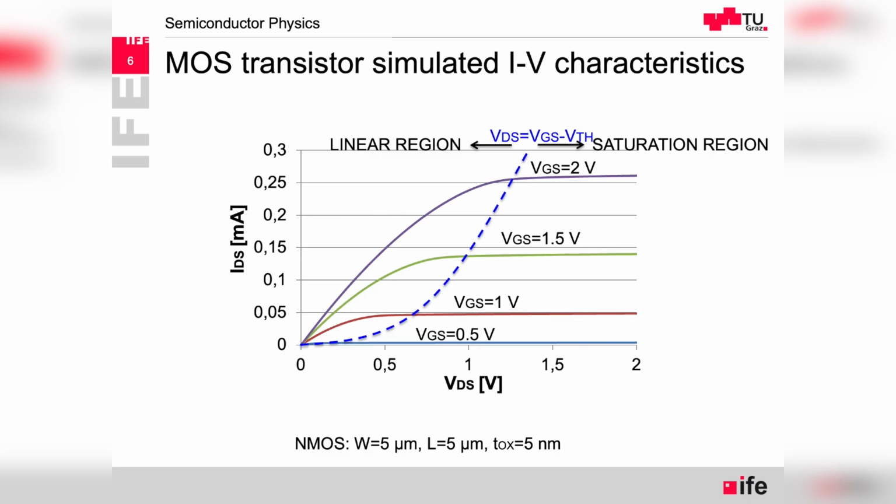So having spoken about the threshold voltage, we can go to the next topic, which is IV characteristics, the drain current as a function of drain source voltage. We have already seen the expression of how the current changes in the linear region and the saturation, and we will be repeating it a little bit. Basically, in the saturation region, the characteristics are flat, but almost flat, and we go to that.